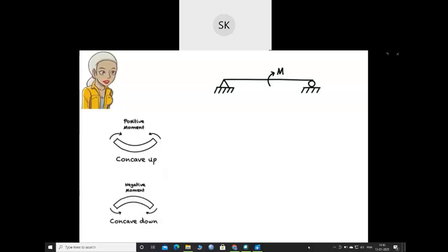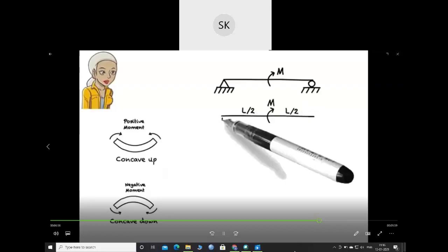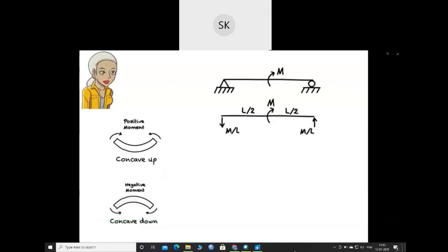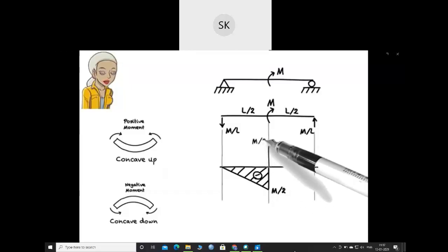Example 4. In this problem, the beam is subjected to a parabolic load defined using the quadratic equation Wx equals 2 over 25 times x minus 5 over L, squared. So the magnitude of the equivalent concentrated load is equal to the area under the curve. This can be done by integrating Wx. The area of the curve is 40 over 3. To find the location of the equivalent concentrated load, we need to determine the geometric center of the area. This is done using this equation.